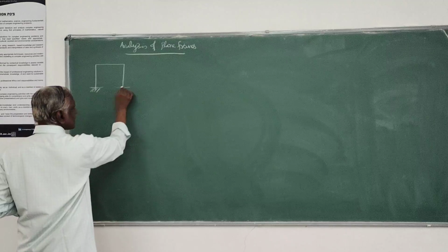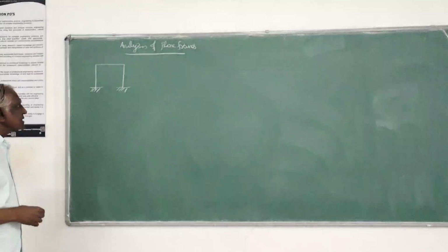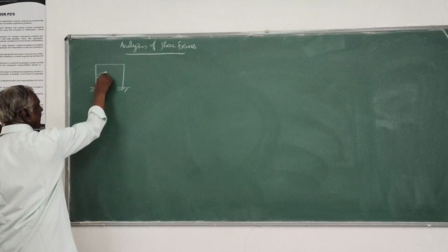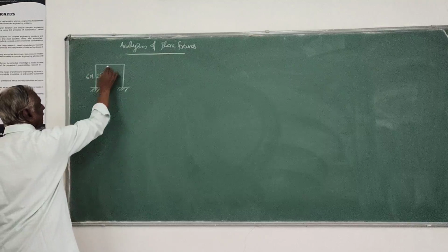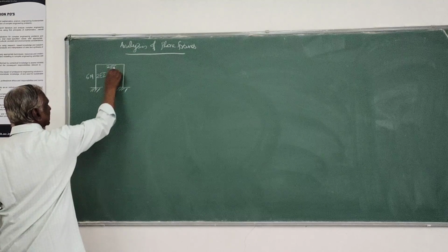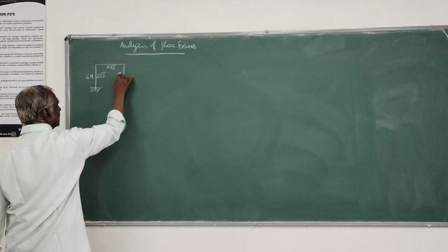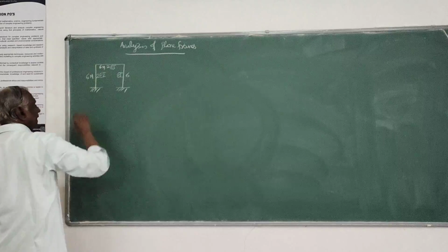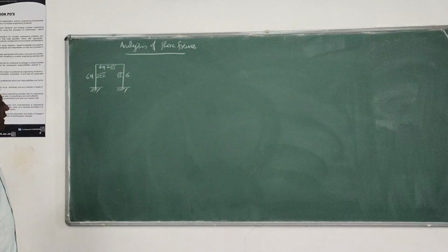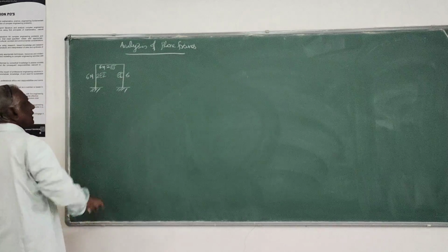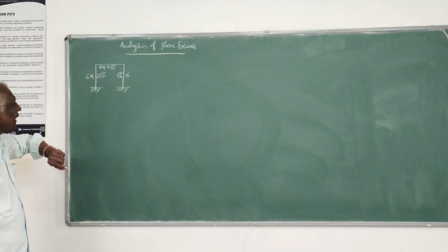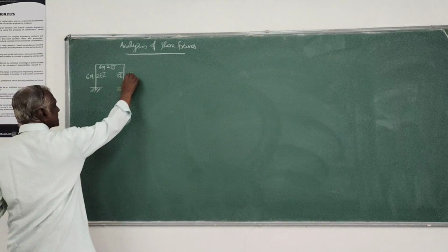Now let us start with the analysis by taking up a problem straight away. So let us take a rigid plane frame structure as shown in this particular figure. Let us take a 6 meter by 6 meter rigid rectangular orthogonal frame of flexural rigidity 2 EI for 2 members, EI for another, and 6 meter is the height for all.